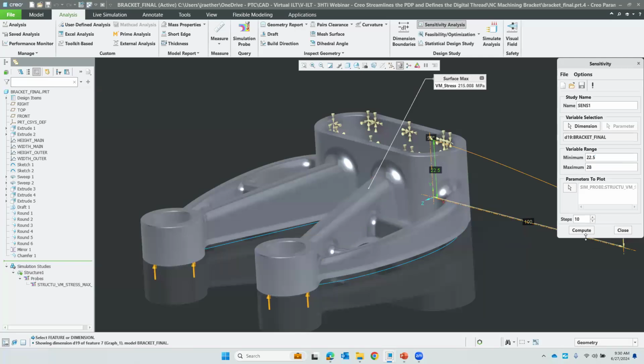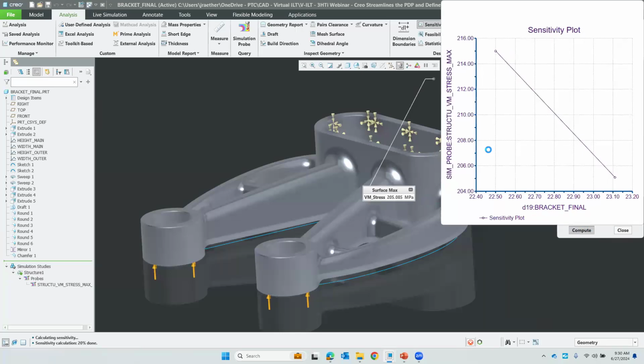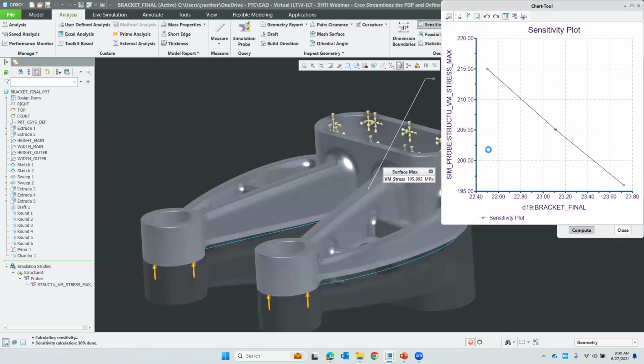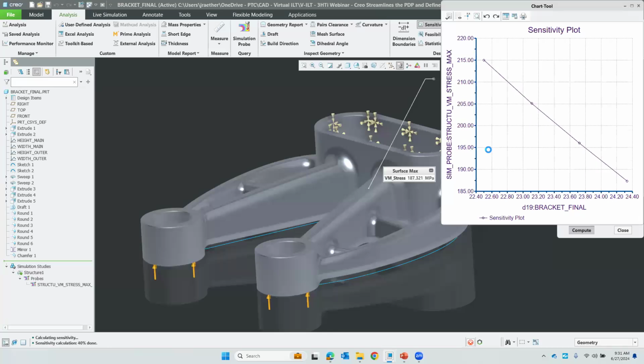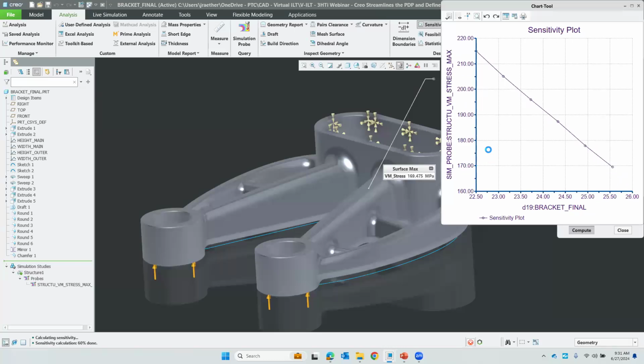So that quickly, I'm going to say, I don't know. Is it worth me working with that? Is that main beam altering the height? Is that going to get me what I want? Because sometimes maybe it looks like we eliminated the stress and maybe all we did is move it to another area. So when we're using behavioral modeling, I can really easily go in and say, how sensitive is that variable to my design goal, which is again, lowering stress. So I could do this manually, but it could take a long, long time. And when you get very complicated models, I could have many different variables.